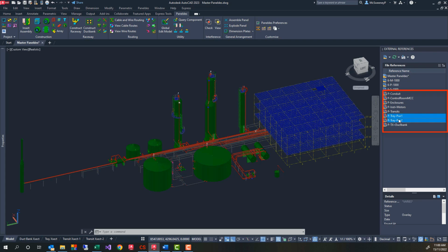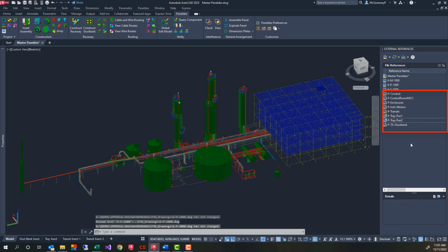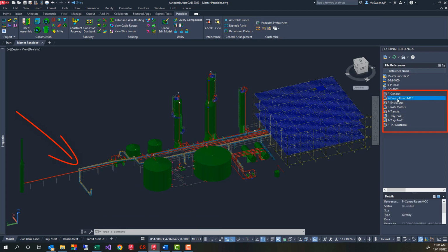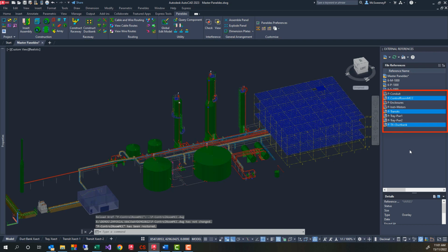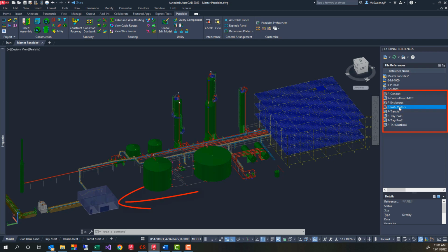Subdividing your electrical model by power levels, e.g. instrumentation or LV, is a good choice, and this can be combined easily with a geographic area subdivision. An example of geographic areas could be the floors of a high-rise building or similar. Another common subdivision is the component type. It is sensible to separate your instruments from your trays and your trays from your enclosures. Single component types also tend to be separated by workflow and personnel.